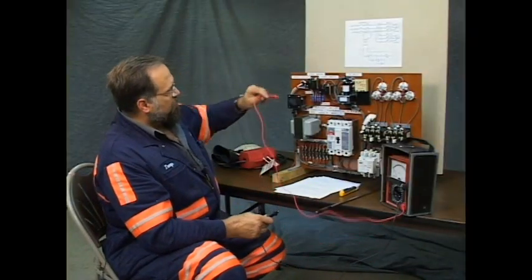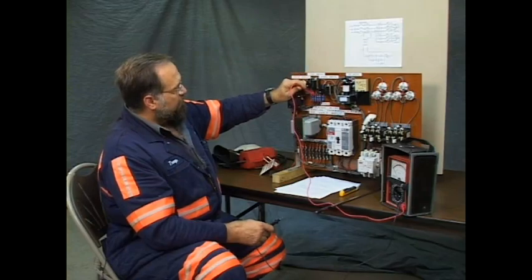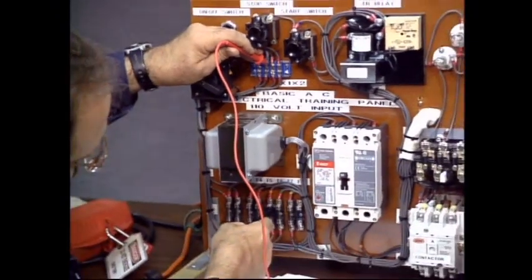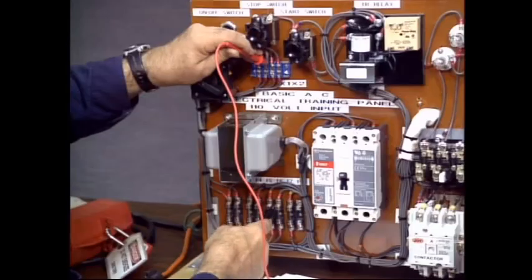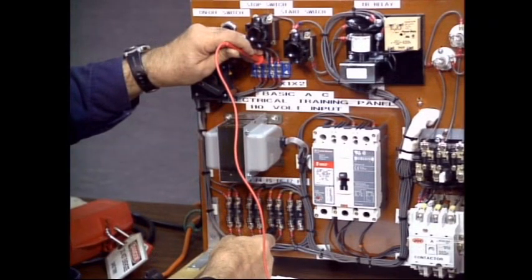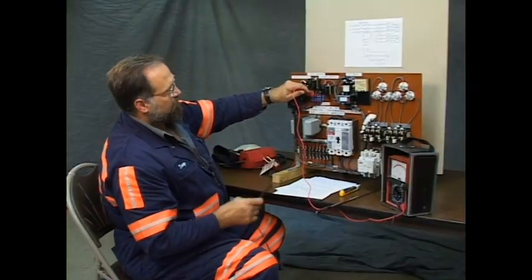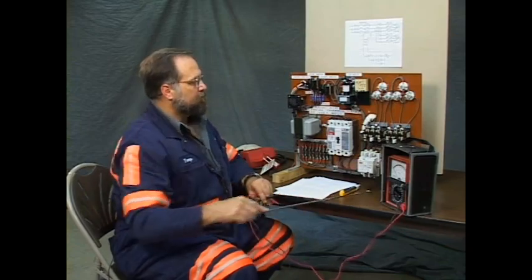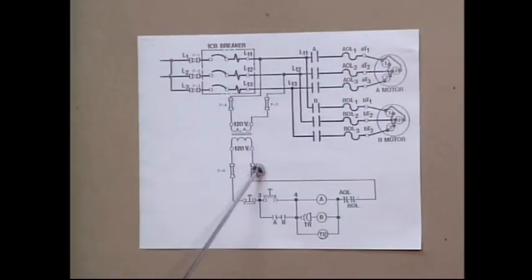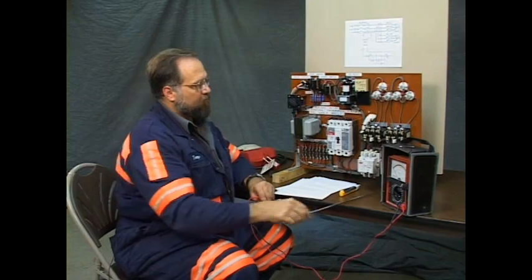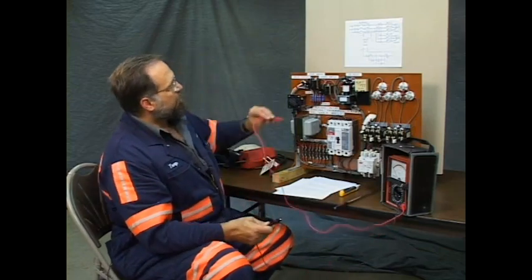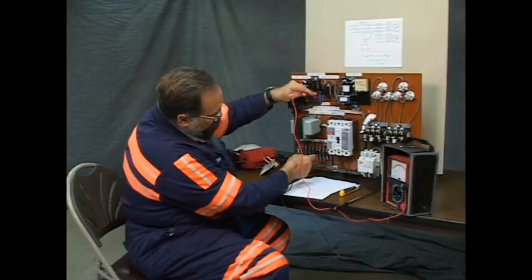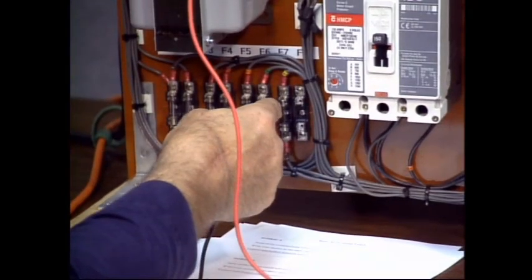And the X1 terminal is here. And I'm going to read to the load side of the F6 fuse. And I have a circuit from the line side of the F6 fuse. Now I'm checking the load side. And we're good. Now, let's keep ourselves in order here. I'm going to complete my control transformer and fuse checks by reading from X2 on the transformer, that's the one on the right, to the line side of F7.